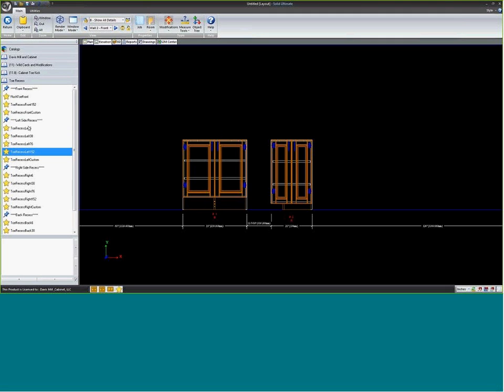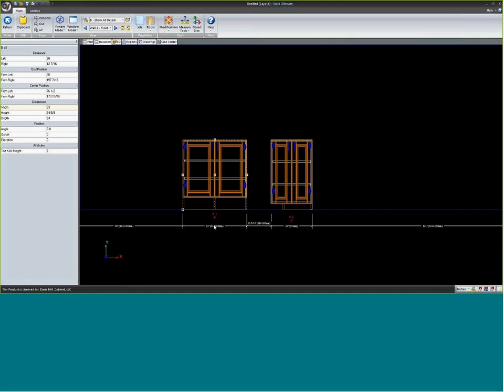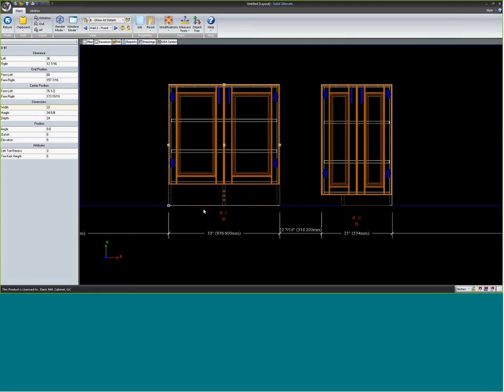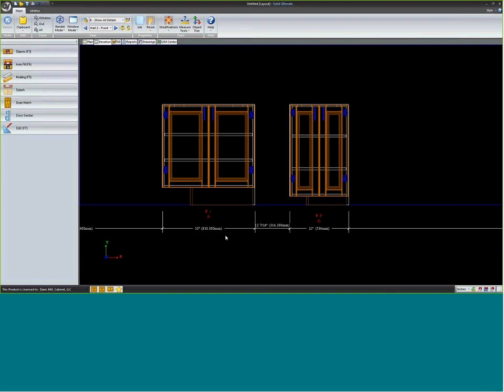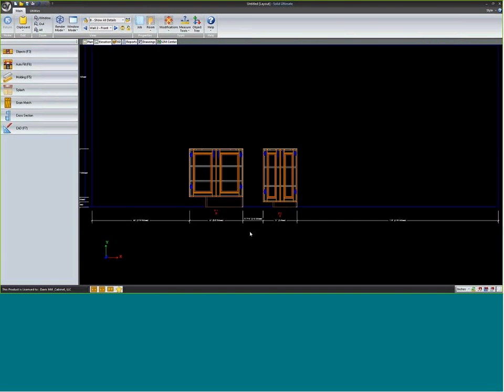I can do the same thing with a custom. Let's recess the left toe custom on this cabinet. Again, nothing happens. If I hit enter 2 times, it just recessed it. But now, again, over here, I have a new sidebar parameter. Left toe recess 3. Let's call it 10, whatever we want to call it. Doesn't really matter. So wildcards do all kinds of things to your cabinets.